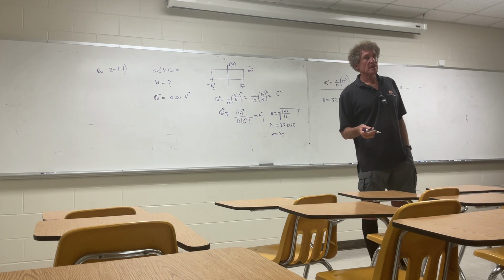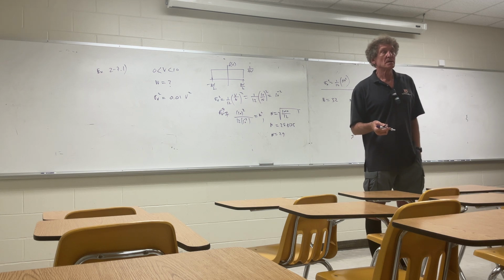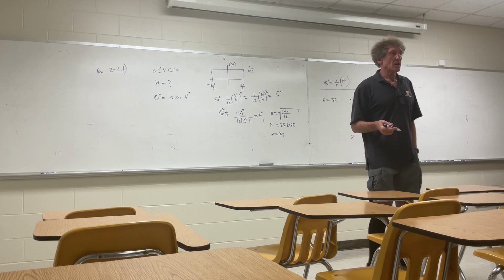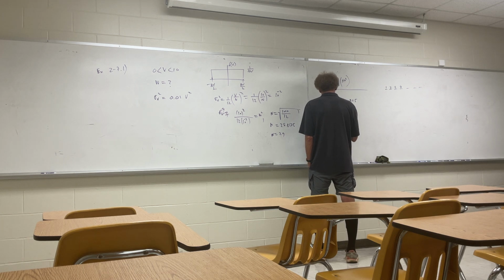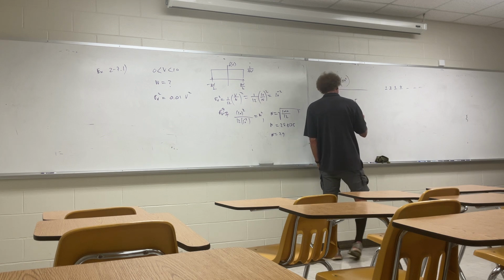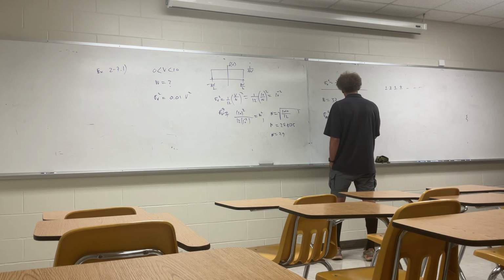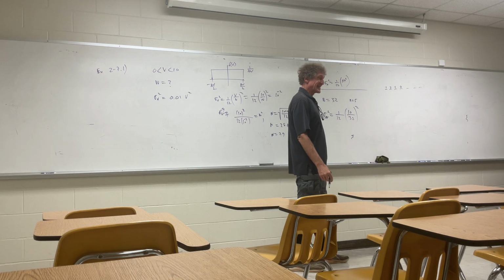What else? If 32 levels are used, what's the actual mean square quantizing error? All right, now we go back to the original calculation. We want sigma of this, we might call it delta V. I'll just call it sigma of V squared. Well, we know that's equal to 1 over 12, and now we have to take the total range of 10 divided by 32 squared to get that. With me? Because n now is going to be 2 to the 5th, or 32.